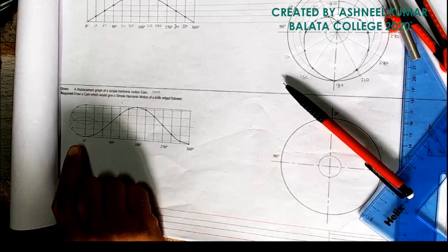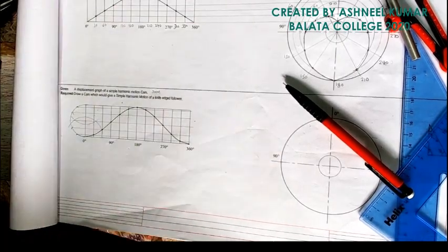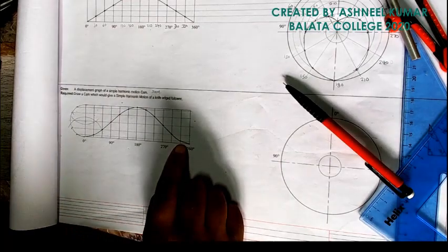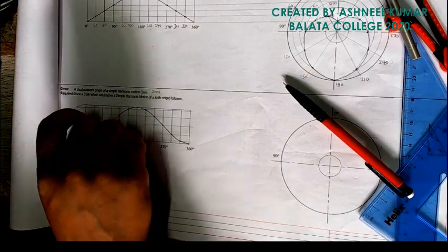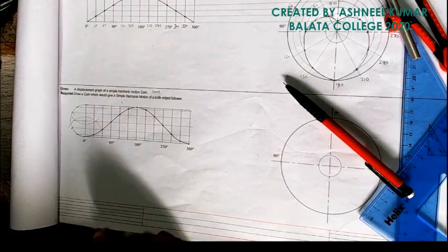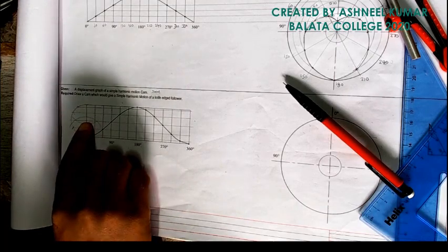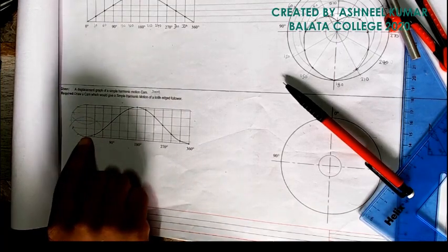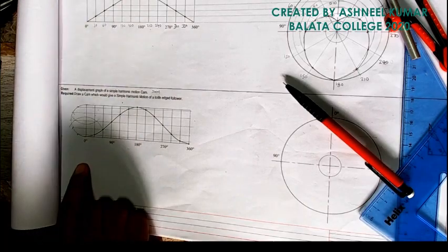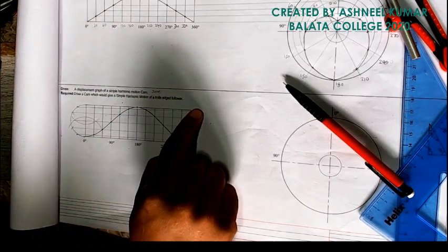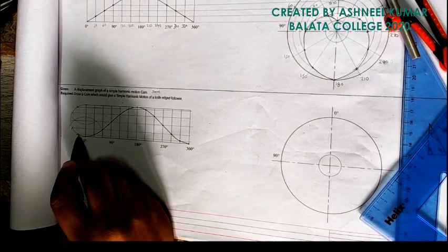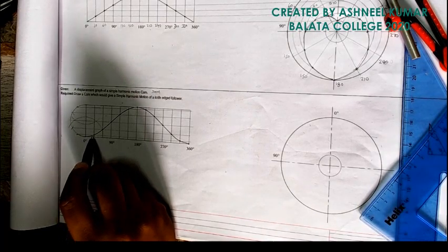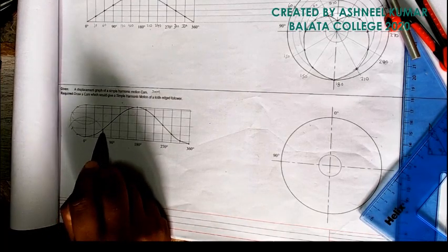Right, so what I have actually done here is to explain you how to get simple harmonic motion. In case this performance graph was not given, but you have to draw a curve which will give a simple harmonic motion, first of all, whatever lift is given there, the maximum lift, you are going to bisect that length. From there you are going to draw a semicircle and divide the semicircle into 6 equal parts. Then you will take all the lines across, right? So now the starting point will be here, first line there, the horizontal and the vertical line where they meet, that's 1 point. The next line here, that's a 1 point.